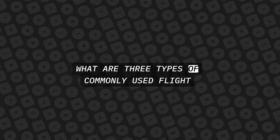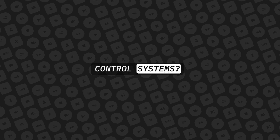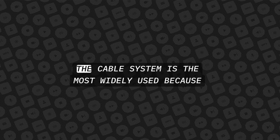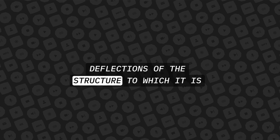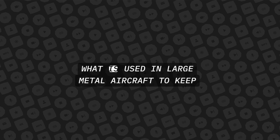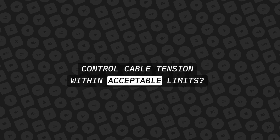What are three types of commonly used flight control systems? They are the cable, the push-pull tube, and the torque tube systems. The cable system is the most widely used because deflections of the structure to which it is attached do not affect its operation. What is used in large metal aircraft to keep control cable tension within acceptable limits?